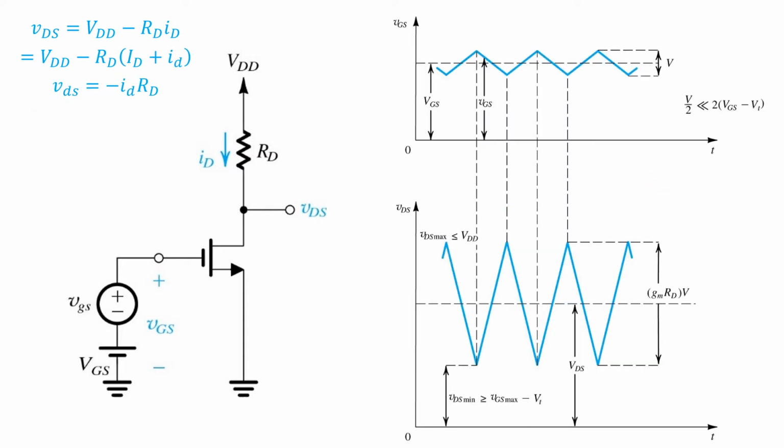Now we've just showed how the output, having an operating point, a small signal part, the small signal component is related to the small signal drain current, a lowercase id, as shown here. You may recall that the small signal drain current, in turn, depends on the small signal gate source voltage. It's Gm times VGS.